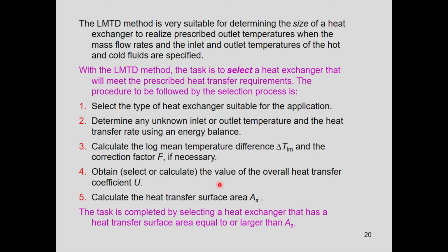Anyhow, I will bring one example in the problem set that will explain how to calculate the overall heat transfer coefficient, so that you will get the idea. So the final step is to determine the heat transfer surface area, and from the surface area you will get the idea of how big or how small the heat exchanger will be.